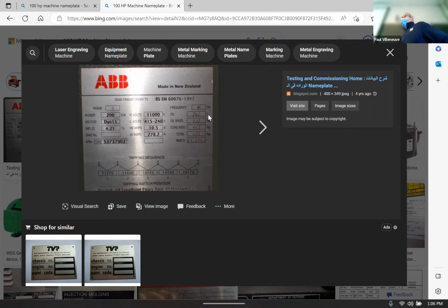What's that? The insulation is typically not heat conductive. It's usually resistant to a certain rise. Like PVC, polyvinyl chloride that you have in your house, that can handle, I can't remember the temperature, maybe 100 degrees C before it starts to degrade. So it's not necessarily good with heat transfer. It's just that it can handle a certain temperature rise. The heat transfer basically has to be like you blow air over it and cool it. But you can get really fancy ones like mineral, I mean, rocks.